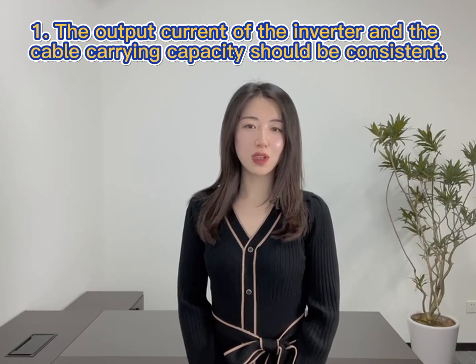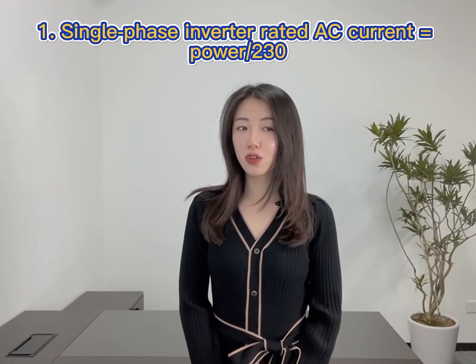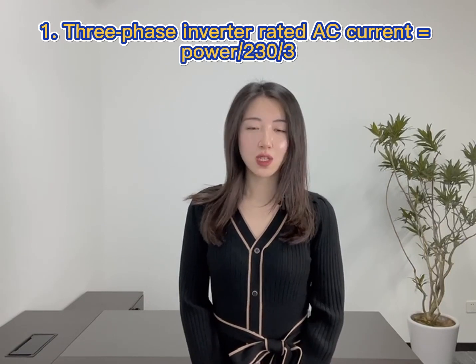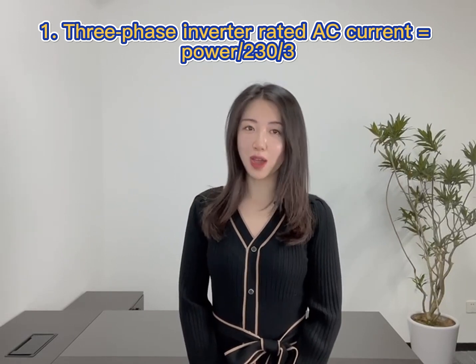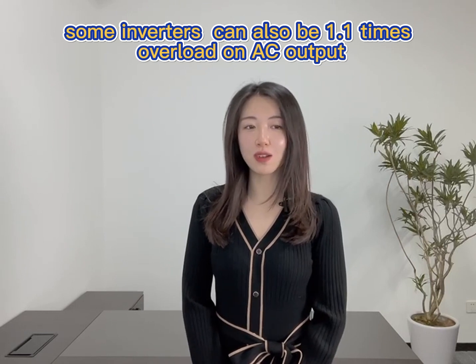1. The output current of the inverter and the cable carrying capacity should be consistent. Inverter output current is determined by power. Single-phase inverter rated AC current equals power divided by 230. Three-phase inverter rated AC current equals power divided by 230 divided by 3. And some inverters can also be 1.1 times overloaded on AC output.